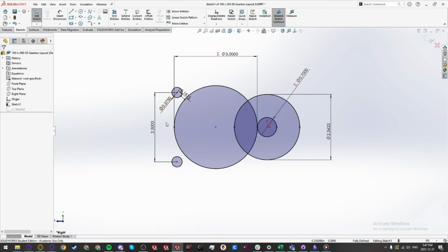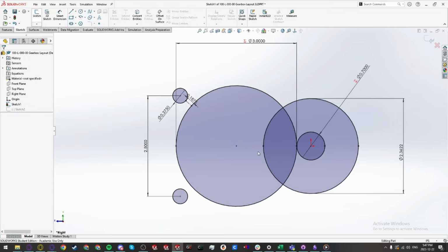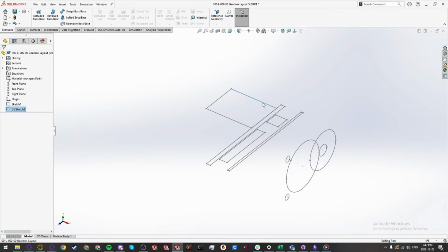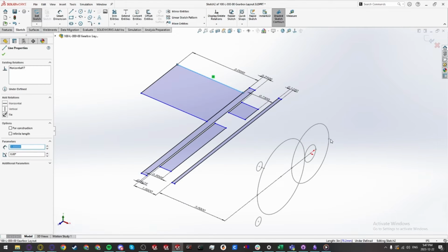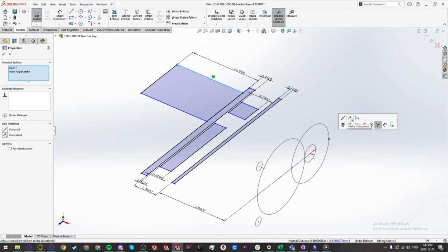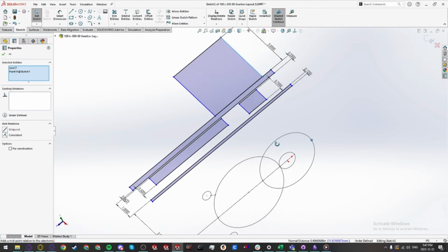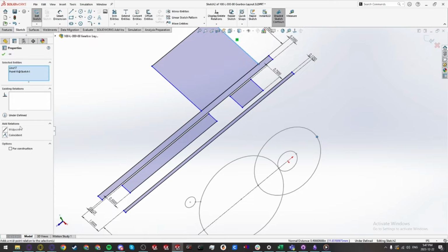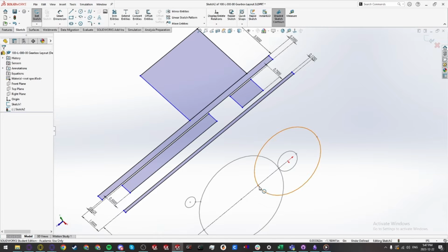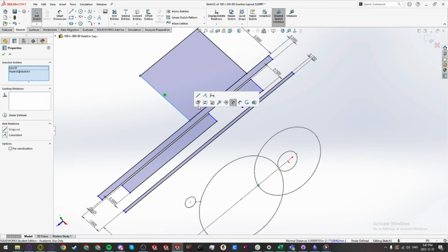My standoffs are not in that top sketch, so I'm not going to put points on that. But once these points are in, I can edit the 3rd dimensional sketch. And I can just select the line, select the point there, and make them coincident. And I can repeat that for the bottom of the motor as well.